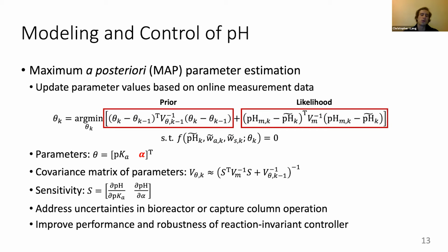Got it. And so when you solve this optimization problem, is it just a gradient descent solution, or how is that done? The optimization algorithm that we have used is gradient descent. Because the size of the model equation is not that large, it is actually computable within a second, which is the time period that we use for the computer computation. But the PLC actually runs very fast, in a cycle of about a millisecond.